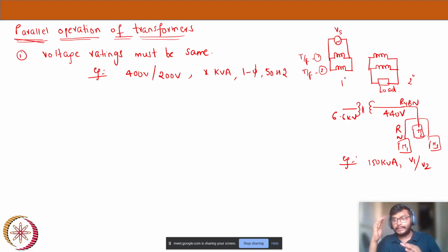Now these homes won't remain the same. As time passes by, let's say after 3 years, there will be more houses in that area. Every day we are seeing many more constructions happening, they're building many more apartments, and in that case my load demand at the distribution side will obviously increase. It will actually double in a period of 5 to 6 years. There is no wonder in that. So at this point, my 150 kVA transformer is okay to support the load at the households. My house and the 2 or 3 houses nearby are happy with 150 kVA.